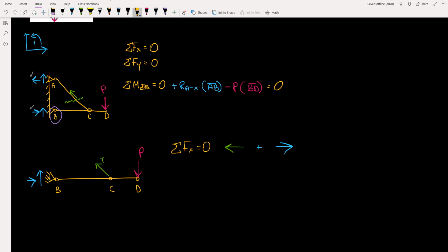So now, looking at this bottom free body diagram, we can of course apply a moment in the z direction at joint C, and we can very clearly see that if we take our reaction, it's going to cause a clockwise rotation about the joint. So we'll have some negative moment, and the applied force is also causing a clockwise rotation, and so it is also negative.